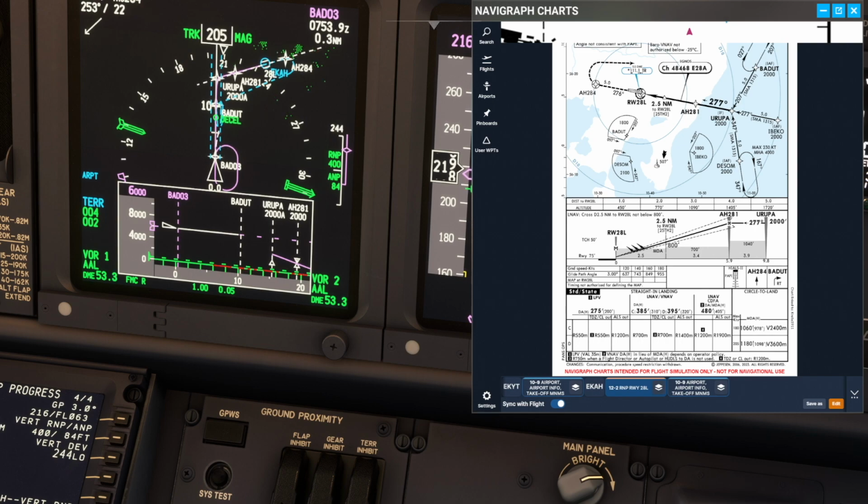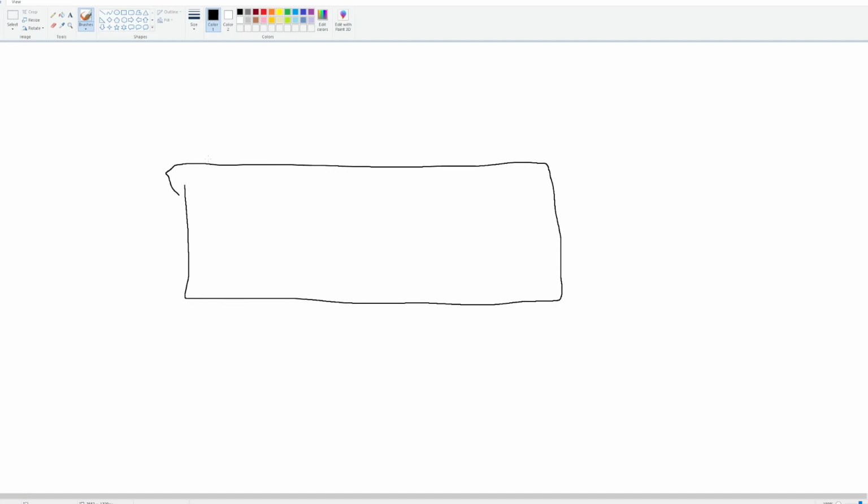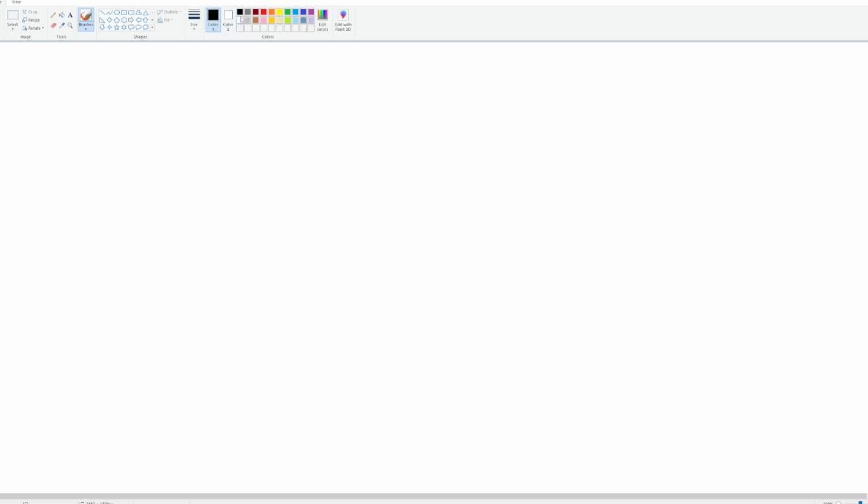So if we go back to the sophisticated explanation tool here, if we imagine we have our VSD in this box here, maybe we have a bit of terrain here, and then we have the airport. Then at some point where we have the runway, it's going to be a white box. It should be positioned exactly on the terrain floor. If it is, then we know that we've set the correct altitude, because this terrain is based upon the terrain database, not reference to the mean sea level. Good. Now, the second way of mitigating it is when we fly the approach.